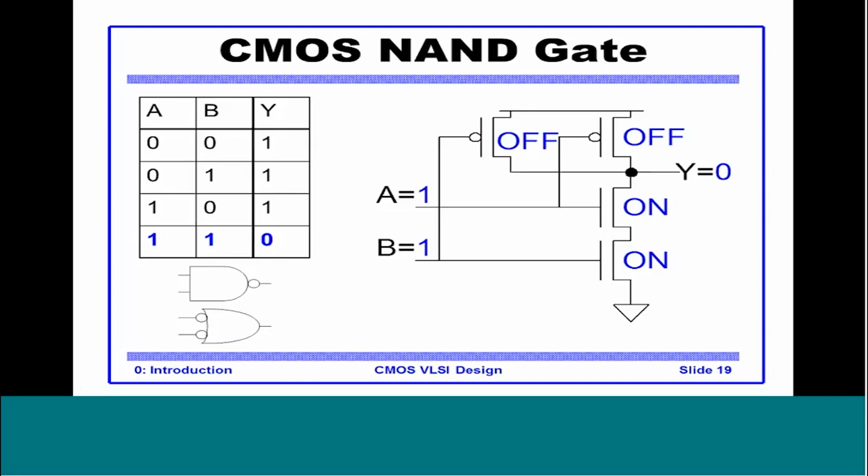So we see that CMOS technology is basically inverted logic. All the basic gates which are lowest in area and lowest in transistor count are either inverters, NAND or NOR. These are the basic gates. All other combinational gates are made out of these three gates. If you remember your basic electronics, this is the reason why NAND and NOR are also called universal gates.